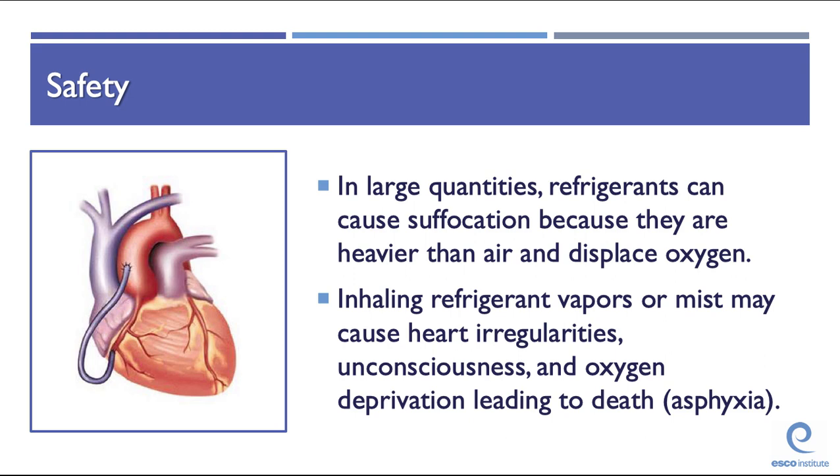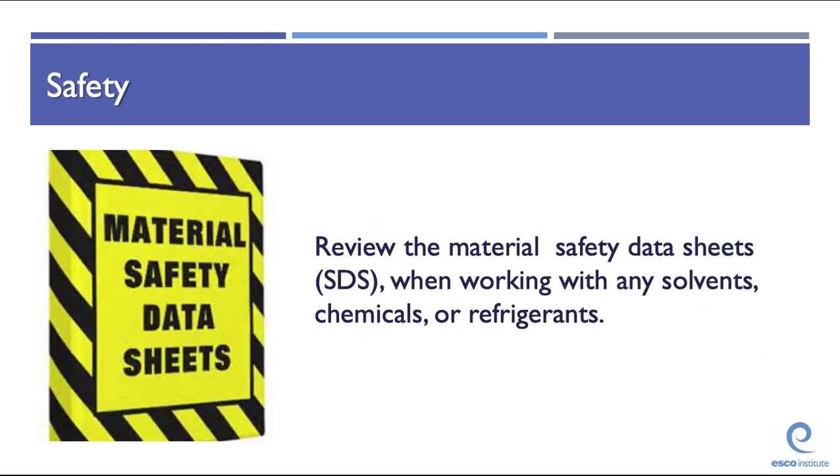In large quantities, all refrigerants can cause suffocation because they displace oxygen. Inhaling refrigerant vapors or mist may cause heart irregularities, unconsciousness, and oxygen deprivation, leading to death. Always review the safety data sheets, that's the SDS, when working with any solvents, chemicals, or refrigerants. Silicone emulsifiers for use in seals or gaskets are not compatible with HFO refrigerants.